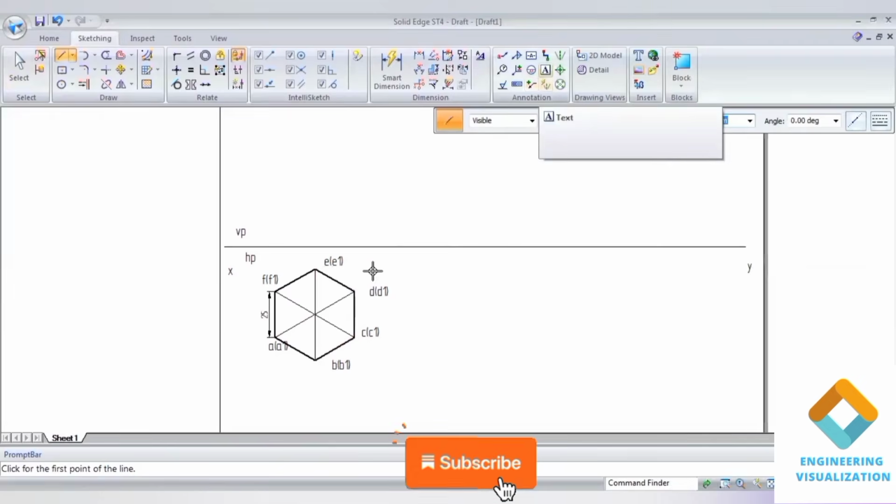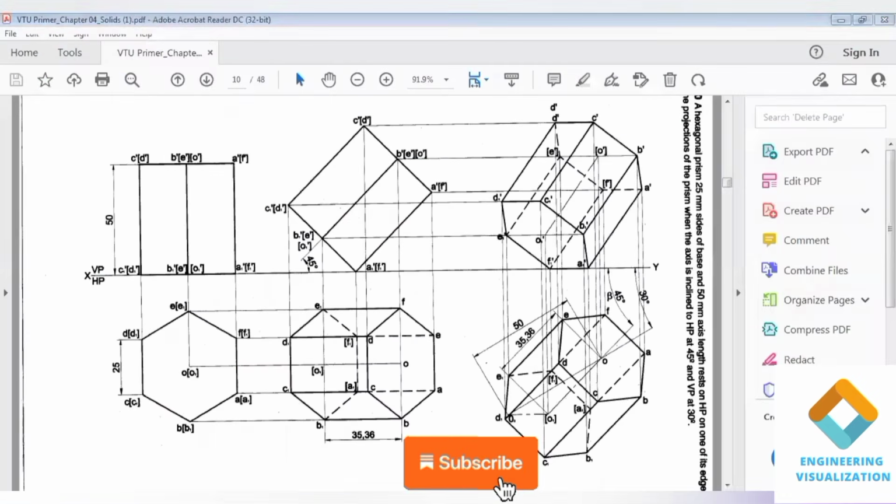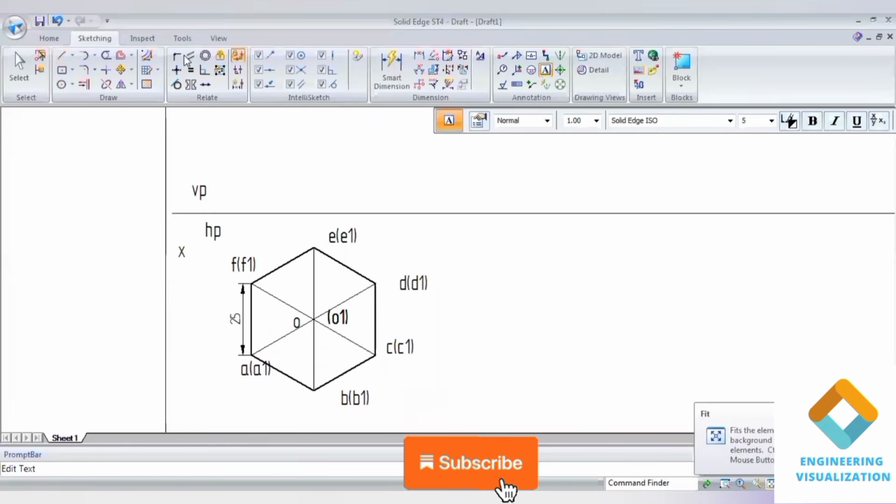Okay, you can see in this problem I have drawn the three thin lines. Since it is a prism we should be drawing only the thin lines, not the thick lines, and mention O1 and close the bracket. Now draw the projection lines upward to complete the front view. So draw the projection lines upward here now.